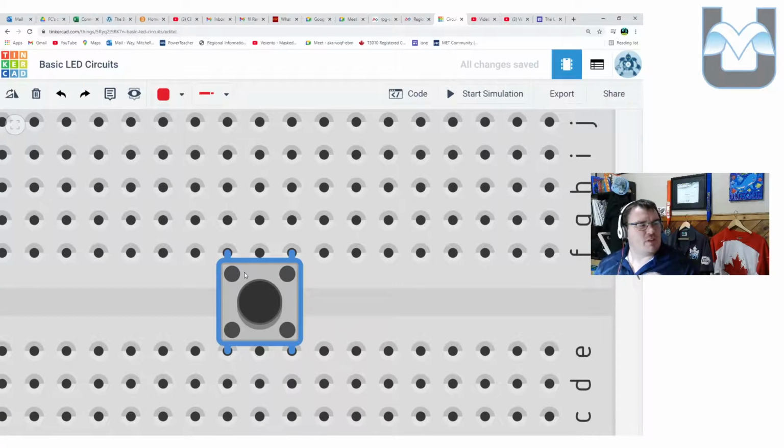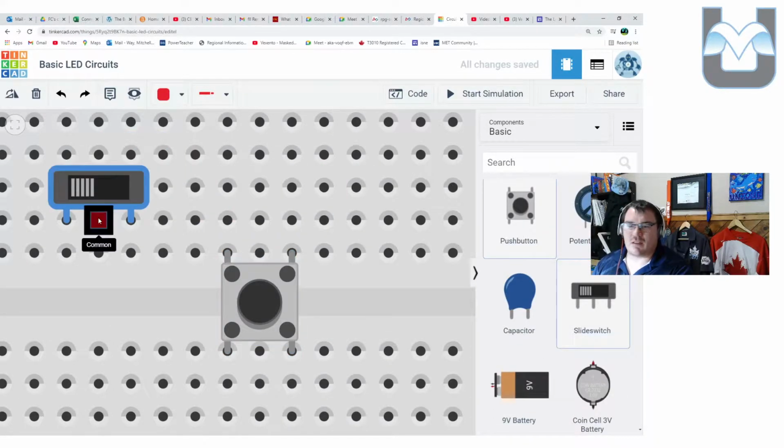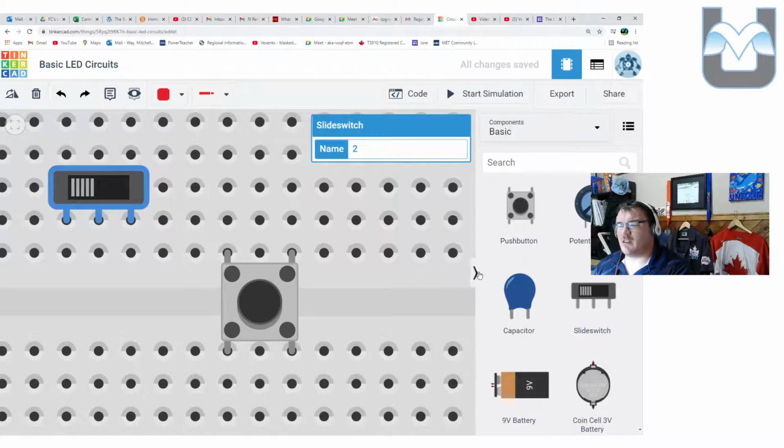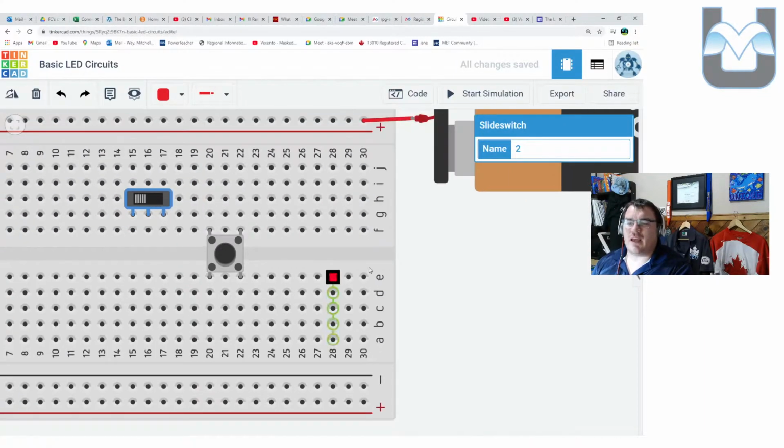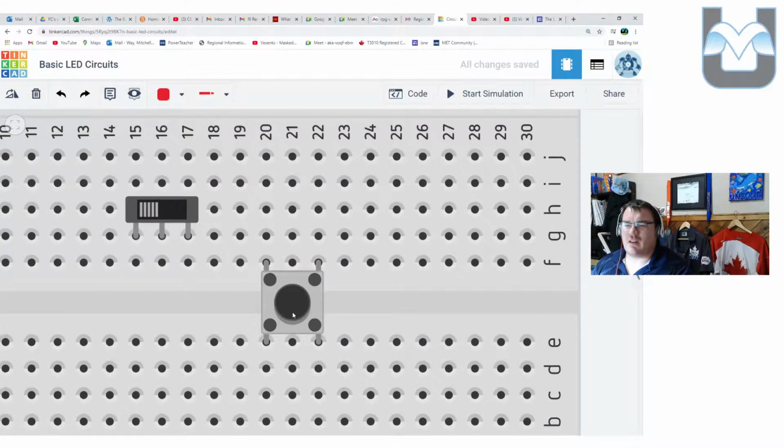Now this is what's called a momentary push button, and it's a normally open momentary push button, which means that we're going to close it, we're going to actually turn it on, when we push the button. They do come in both kinds depending on your application. There's a few other versions of this that are basically the same, including things like slide switches. And I think we'll actually hook up a slide switch here too, just to learn how they work. In both cases, these are going to stop or start electrical flow through the part when we do something mechanical. So the term we'd often use is a mechanical device here. We're going to move this in some way and we're going to change the electrical flow.